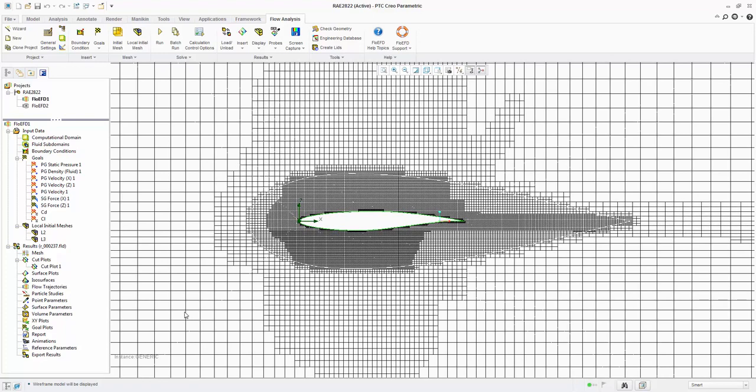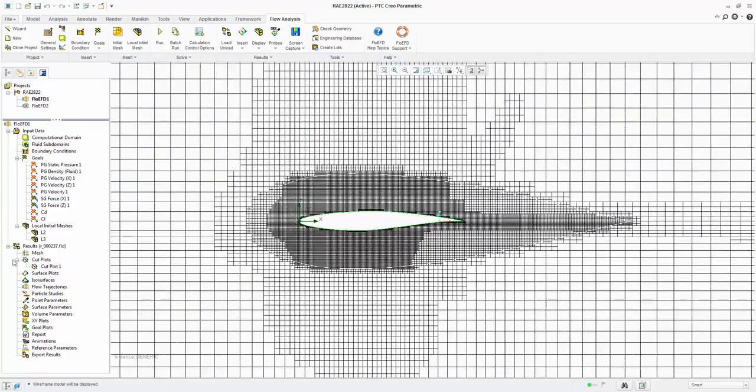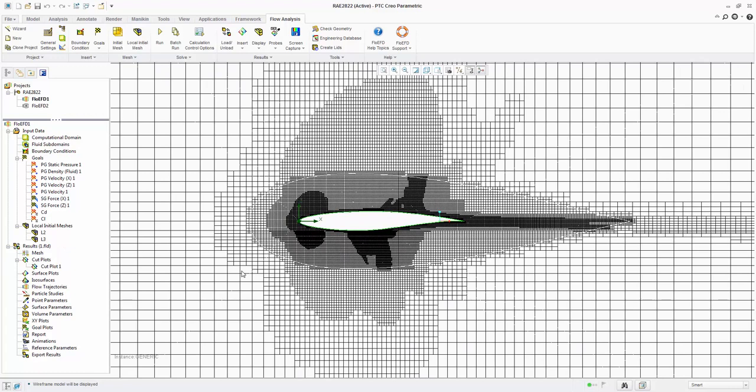Loading in the next mesh, we have an approximate count of 150,000, about 5 times as many. Showing the cut plot, we can see the mesh refinement which has occurred. We can now see a spread of level 3 grid cells in our mesh volume and some level 4 cells at the wing surface. The mesh refinement also occurs in the wake zone behind the wing to capture these flow gradients in higher resolution. The final mesh has over 580,000 grid cells, which is a significant jump.